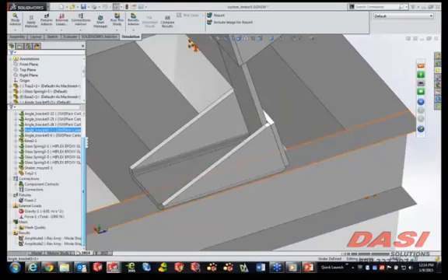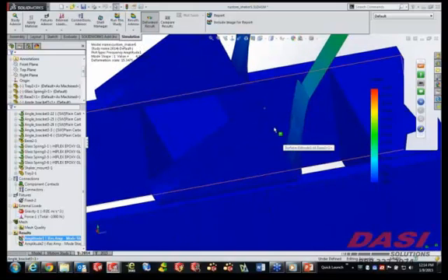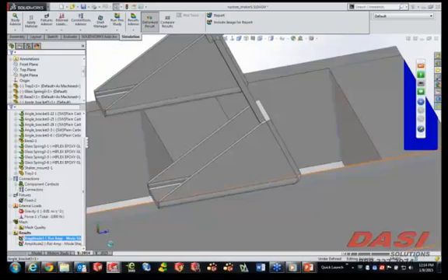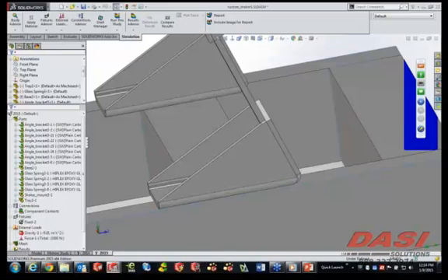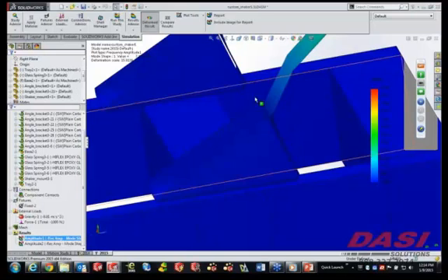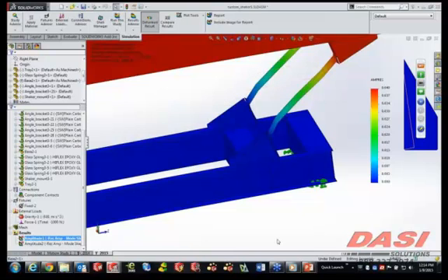So when we do a stress plot or an amplitude in this case, this part would actually peel away from itself because there was nothing bonding this flap to this part of the sheet metal component. Well, now in SolidWorks 2015, those types of sheet metal components with adjacent faces are automatically going to get a global bonded contact. So in the 2015 simulation, if we look at the same parts, you'll see that the sheet metal part holds true and creates a much more sturdy representation of what that file is here to do. So a couple of really nice additions just in quality of study and ease of use moving forward with these tools as well.